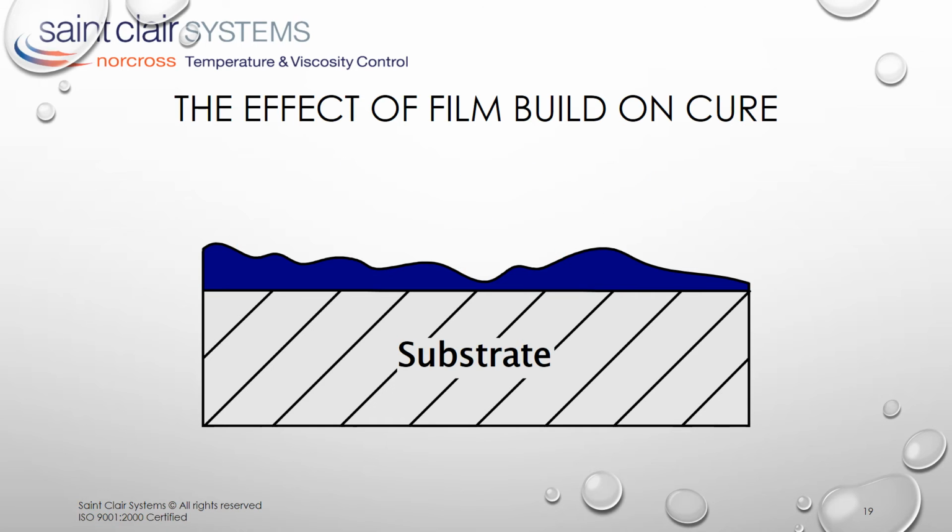In both instances, it's also possible to create blisters, either from solvent or air entrapment under the cured surface of the coating. In the case of UV coatings, this can also represent uncured material, especially a problem in pigmented coatings when the lower layers are shadowed and do not get enough light to cure them in the time allotted.